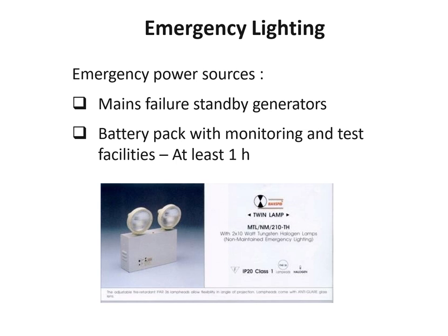Usually those standalone units, in the industry we call Mickey Mouse lights, because they look like two Mickey Mouse ears. These are commonly used as a kind of emergency lighting solution. It comes with its own battery pack, whereas although you can route the lights to the standby generators, usually we use the standby generators for more important functions, like purging or the lift.